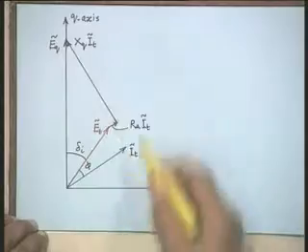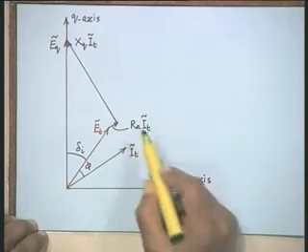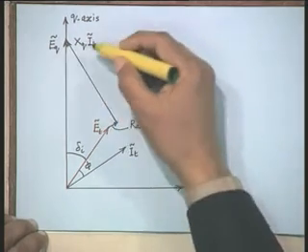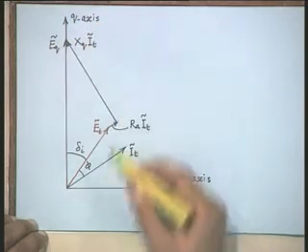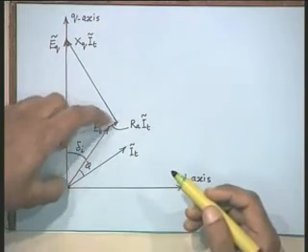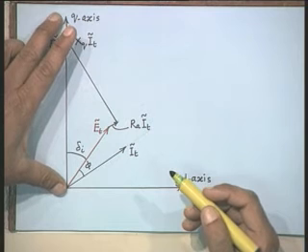And therefore, the phasor diagram which I draw here showing this ET plus RA IT plus j XQ IT gives a voltage EQ. That is, with respect to this terminal voltage ET, the position of EQ comes out to be along the q axis.